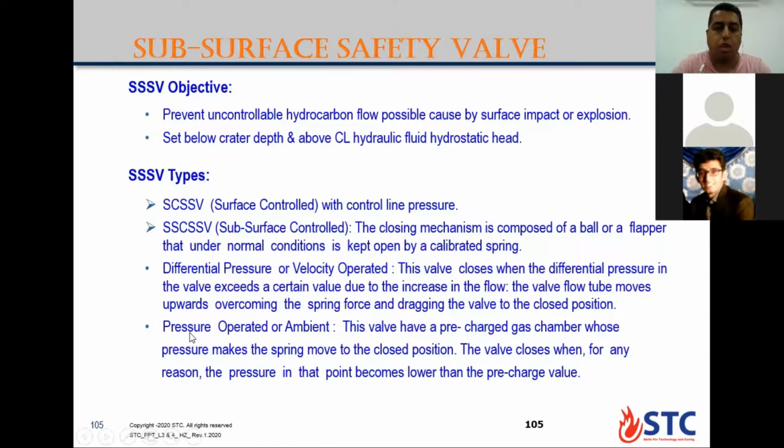Another type works on pressure operated or ambient. This valve has a pre-charged gas chamber. The gas chamber has pressure charged at the surface. That pressure makes the spring move to the closed position. If this pre-charged chamber pressure is drained, the valve will be closed again.